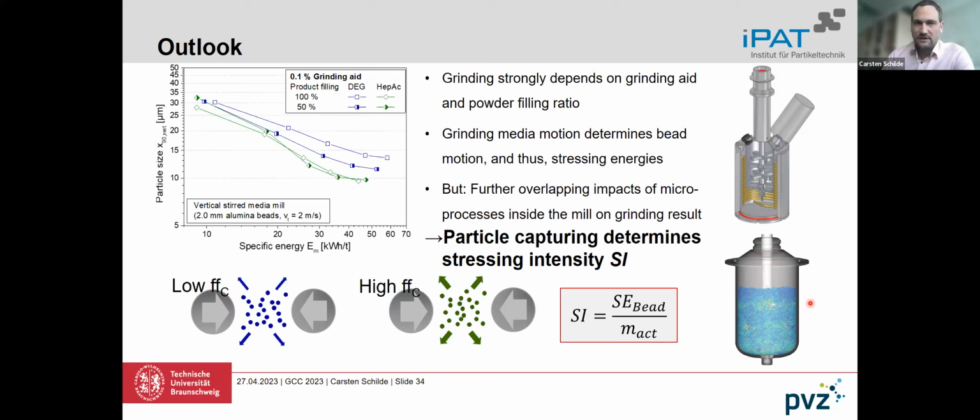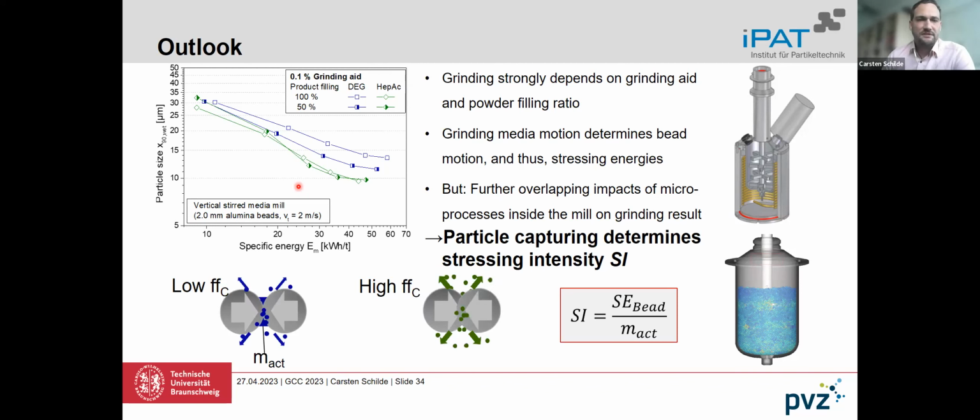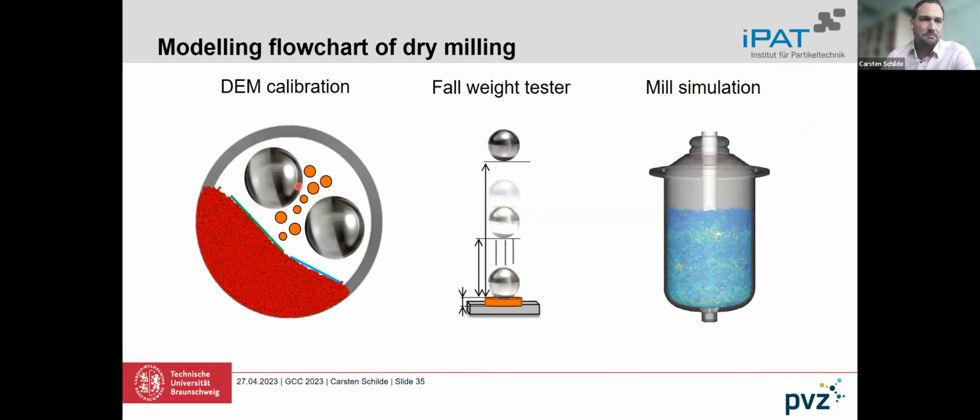That's the reason why grinding processes with different grinding aids, given here on the slides, top left, have different grinding results depending on the flowability, even at similar operating parameters. And normally the DEM simulation will give you the same results. The question is, what's happening with the stressed bulk in between the particles and how the energy is distributed to these particles.